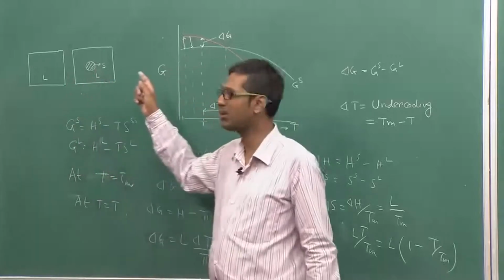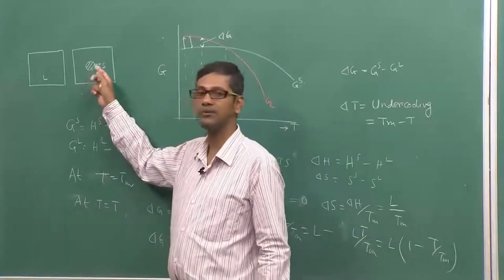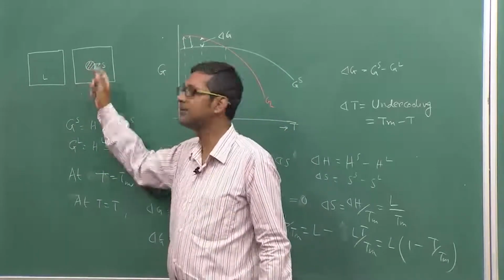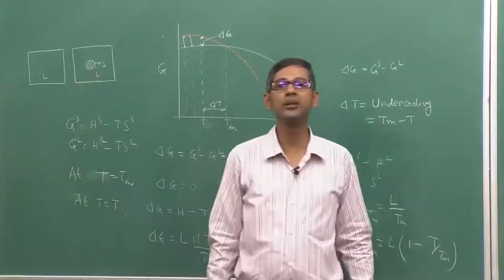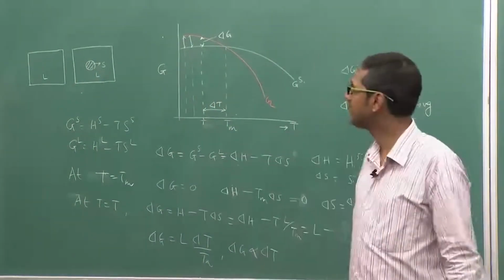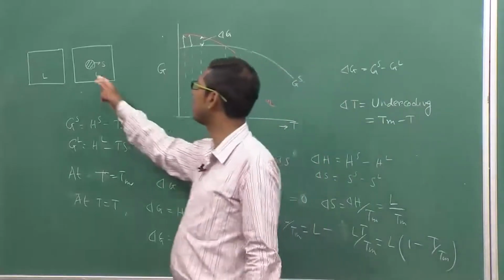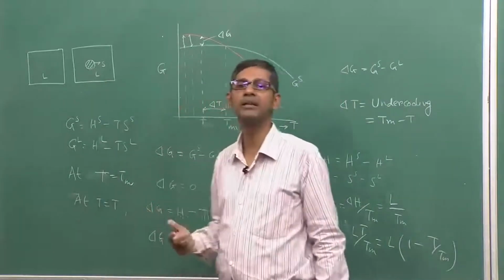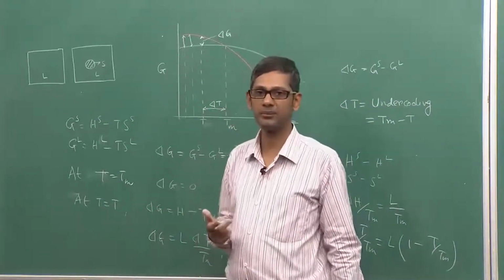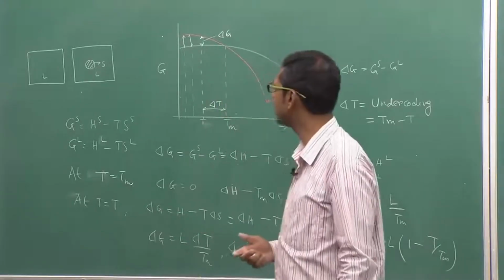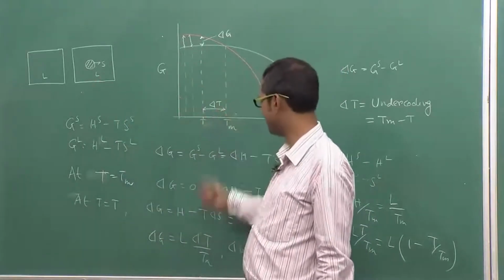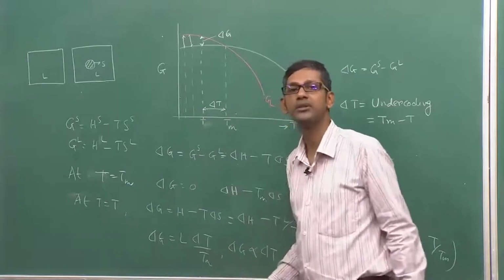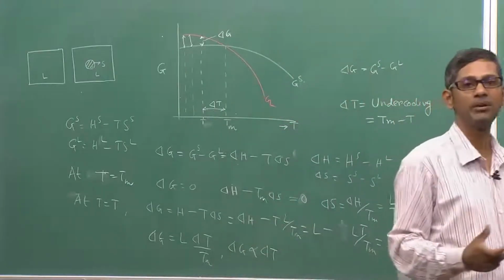We have discussed a lot about these things in the previous few lectures. Because of the broken bonds between the solid and the liquid, there will be interfacial energy, and because it is related to the broken bonds at the interface, it will be a positive energy of the system. This energy must be provided by the free energy available to the system to form this stable form of a nucleus.